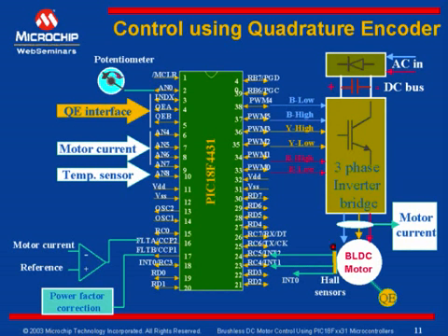In this case, Hall sensors are used for commutation. So these Hall sensors are connected to interrupt pins INT0, INT1, and INT2. And all other hardware description holds good as before. We have seen how 6 PWMs can be interfaced to control 3-phase inverter bridge, and how motor current can be compared and generated a fault input to shut down the PWM in case of any overcurrent situations.